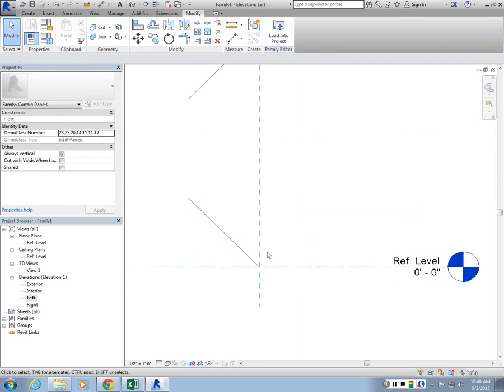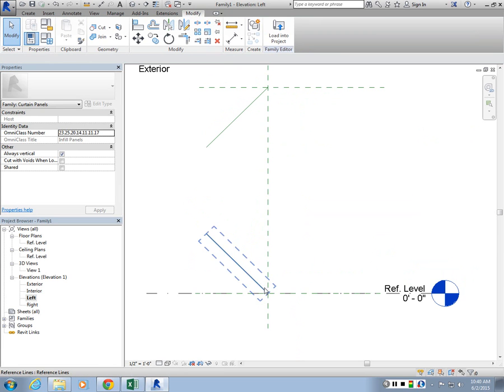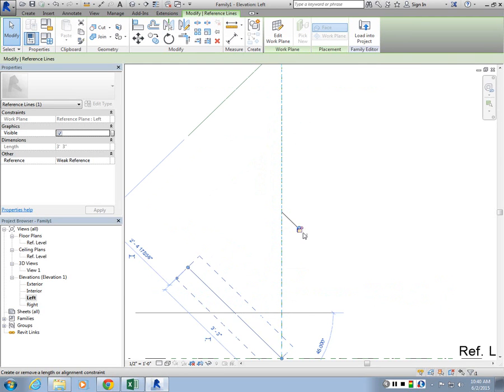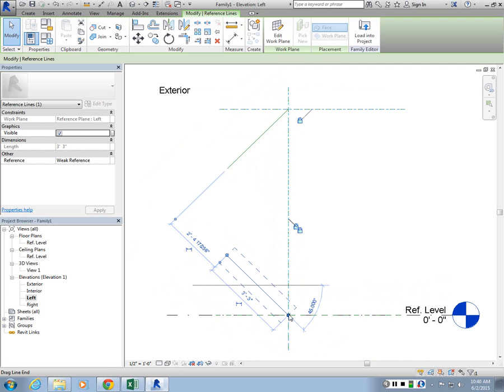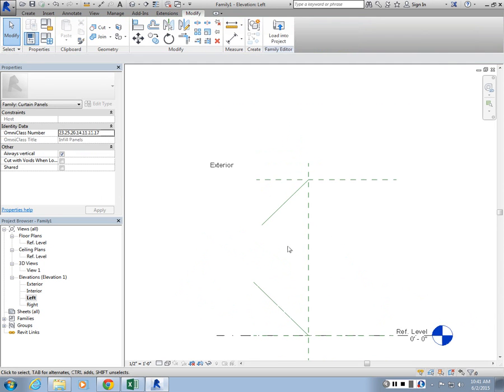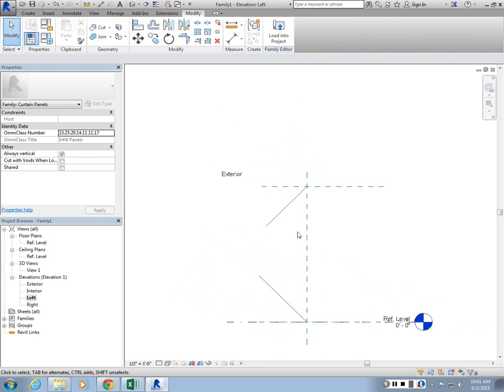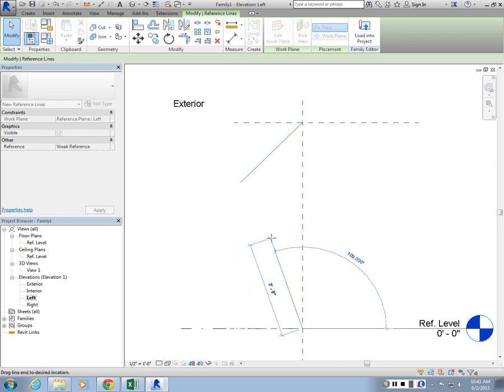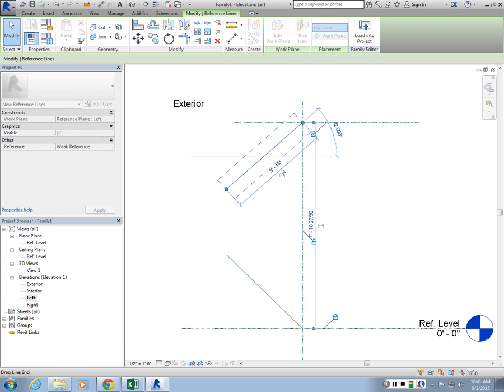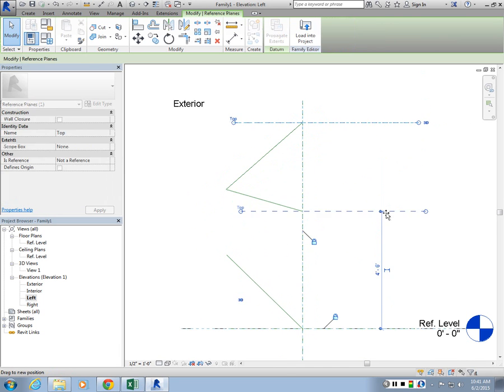I'm going to do the same thing to the guy at the bottom. So I'm going to click here. They are overlapping here, lock this constraint, and then click here, lock this constraint, so that it can rotate freely in this direction. Okay? And then try flexing it to see that it's locked.